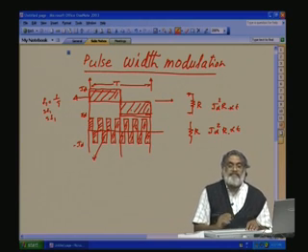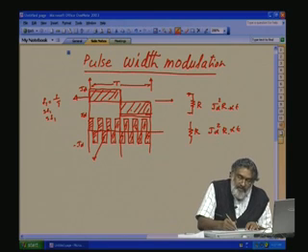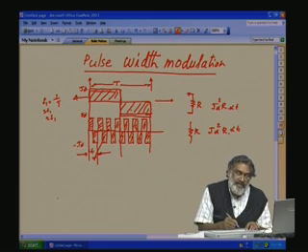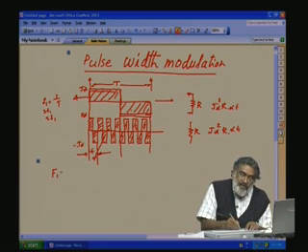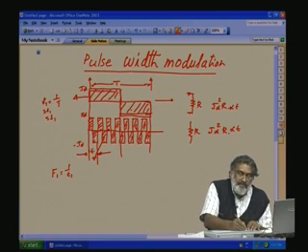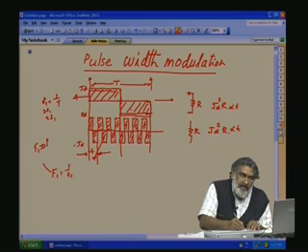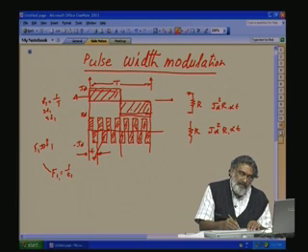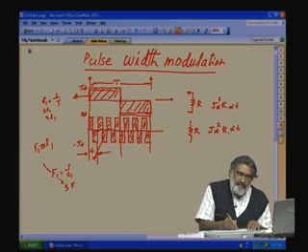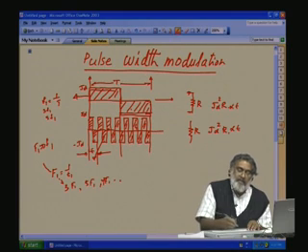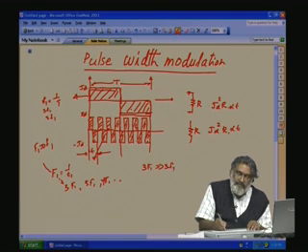Now, how about for this one? The fundamental frequency will be, let us see, this is small t. So, the period is much less. So, the frequency F1 for this one, equal to 1 by T1, is much higher than the other one. So, the harmonics, the multiples of this one, 3F1, 5F1, 7F1, all these harmonics will be much greater than the 3F1, 5F1 of the first waveform.